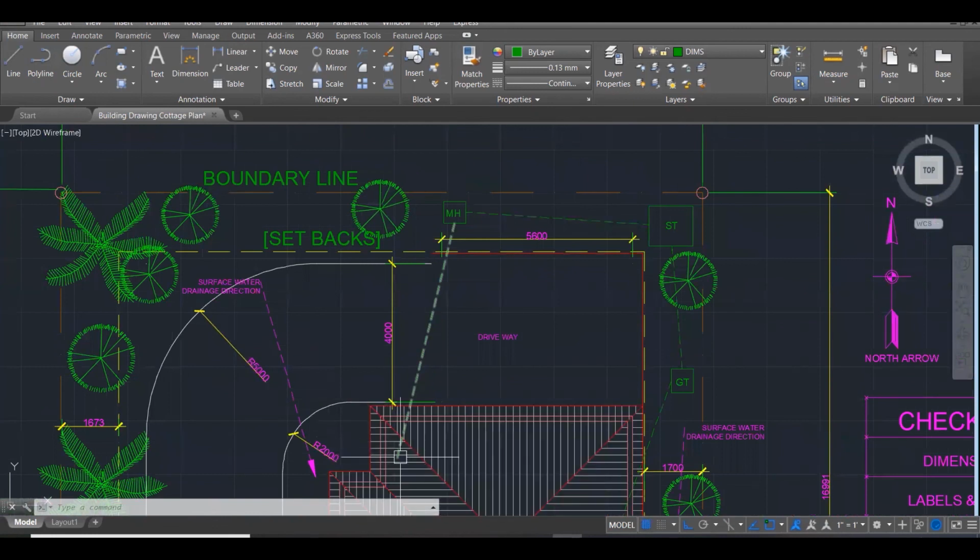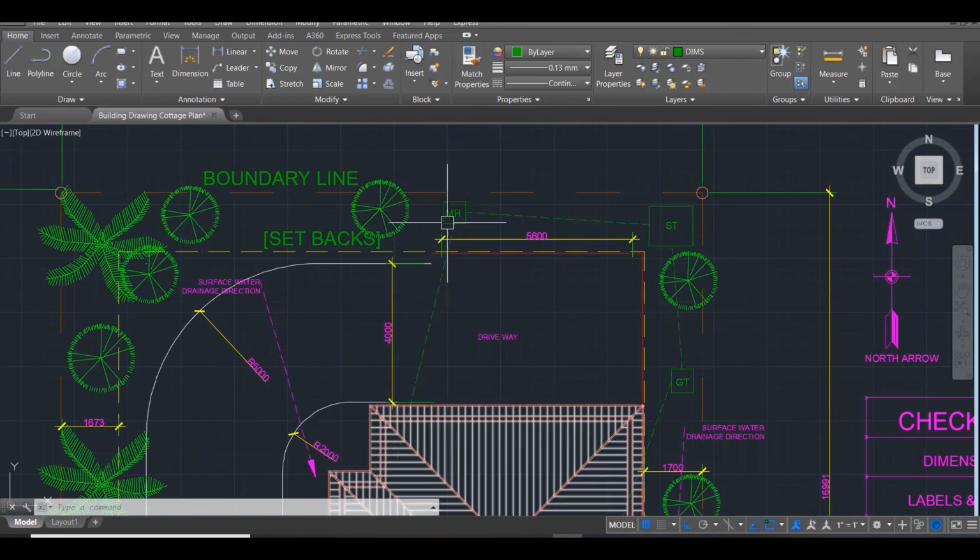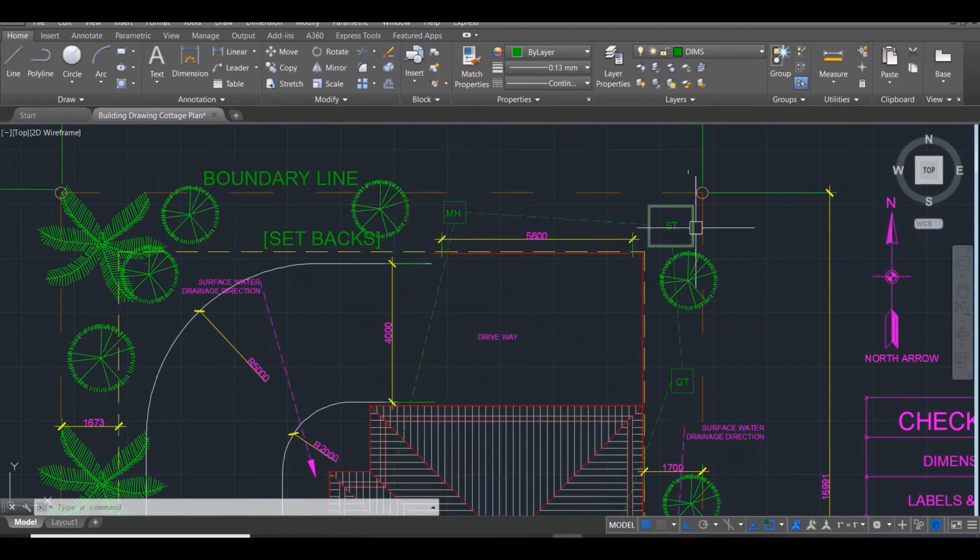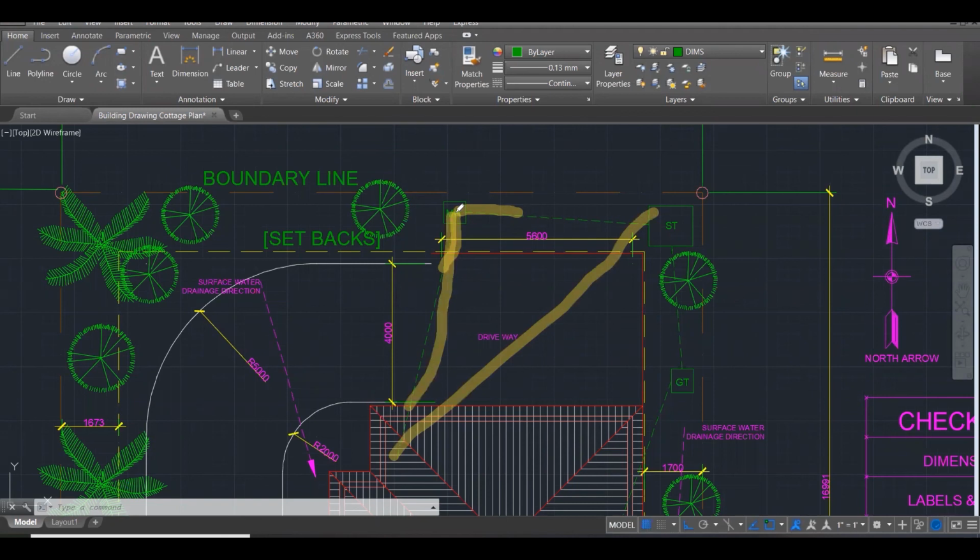Over here is a manhole. That is also a chamber that you can inspect to make sure the waste is going smoothly before it goes on to the septic tank. And the reason why these manholes are invented is we try not to bend the pipe in this 90-degree. So if I need to get from here to here, and that distance might be too long, I will go here, and then I will create a channel, a manhole, and then I will just connect it over to the septic tank.